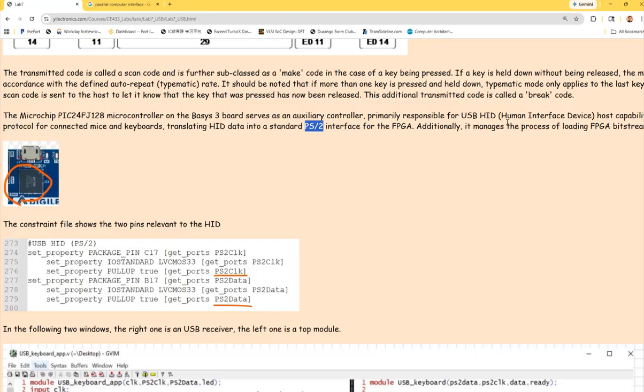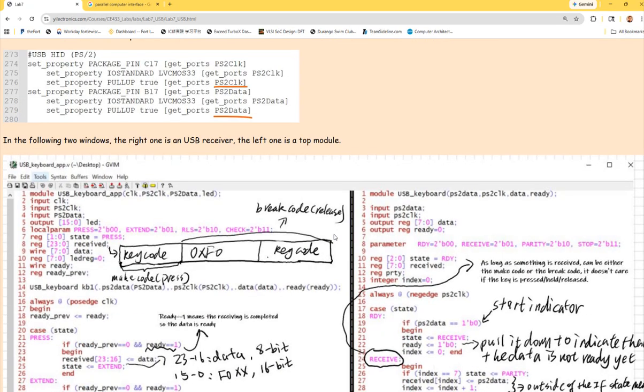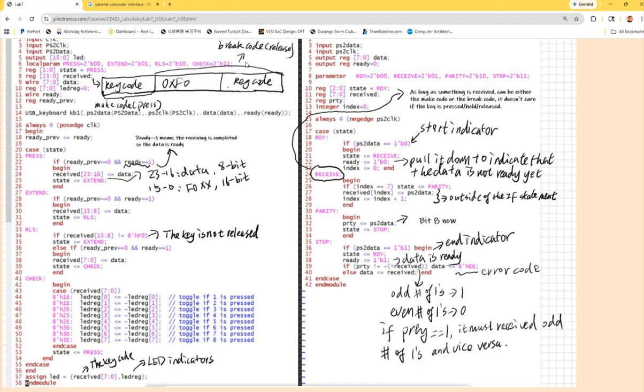I mean, you imagine how you would do that with the microcontroller, with the Arduino. It could be challenging, I think, if it's just an Arduino. So this is the strength of the FPGA, just so flexible. And Arduino, if you want to use Arduino, use a C language to describe the hardware like this. You'll put a lot of lines, and it's odd, right? You're writing C language and combining with interrupts and delays to form that timing. It's not really convenient. So you can see sometimes you prefer FPGA, sometimes you prefer microcontrollers, right?